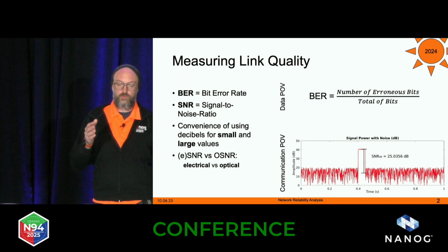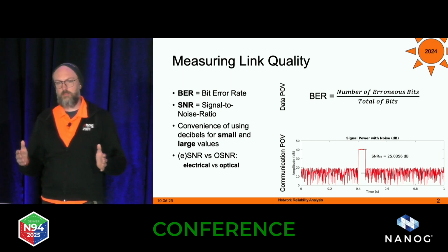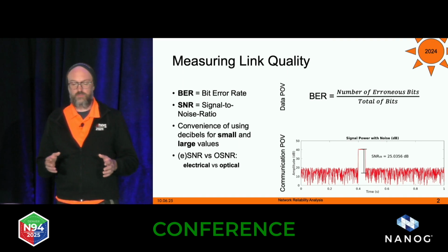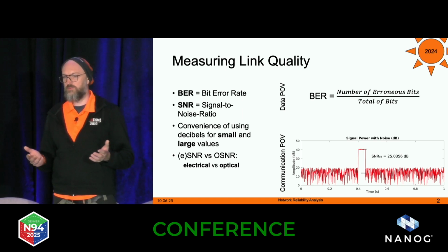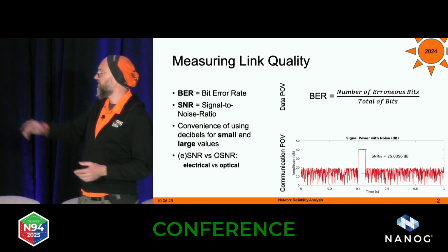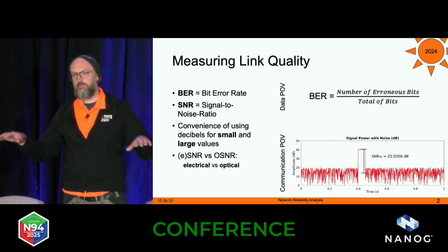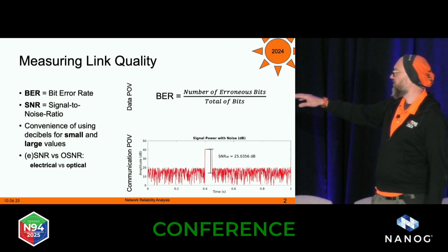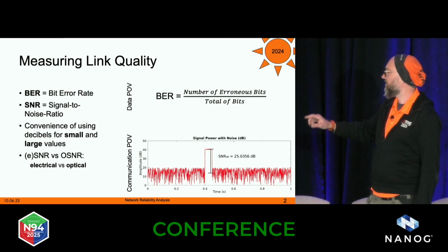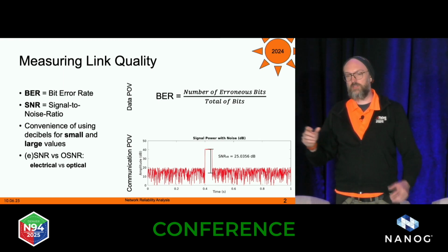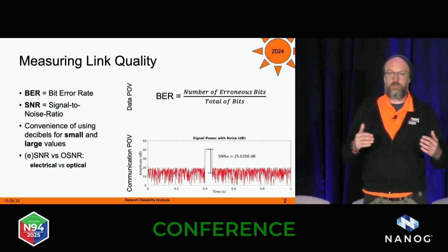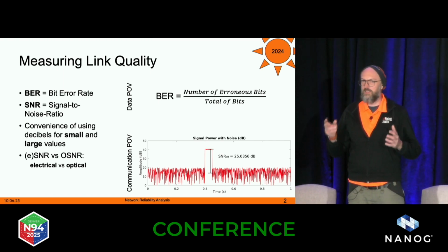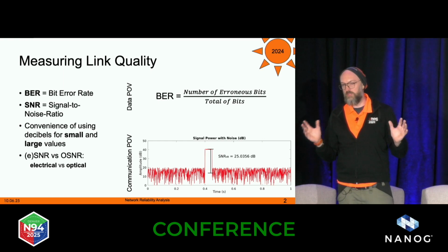The folks doing mainly data transmission, like DWDM, metro or long haul, do not care that much about bit error rate. They focus more on the signal to noise ratio. What is the signal to noise ratio? You see this on the lower graph. On the bottom, there is the noise level, like in this audience now, it's very quiet, so no noise at all. Then there is the desired signal, which we see with our margin of 25 dB. The goal is to have a big margin between the desired signal and the noise level, because otherwise, if this margin is eaten up, and we are basically talking about 20 up to 30 dB, 30 dB is the maximum we can get,